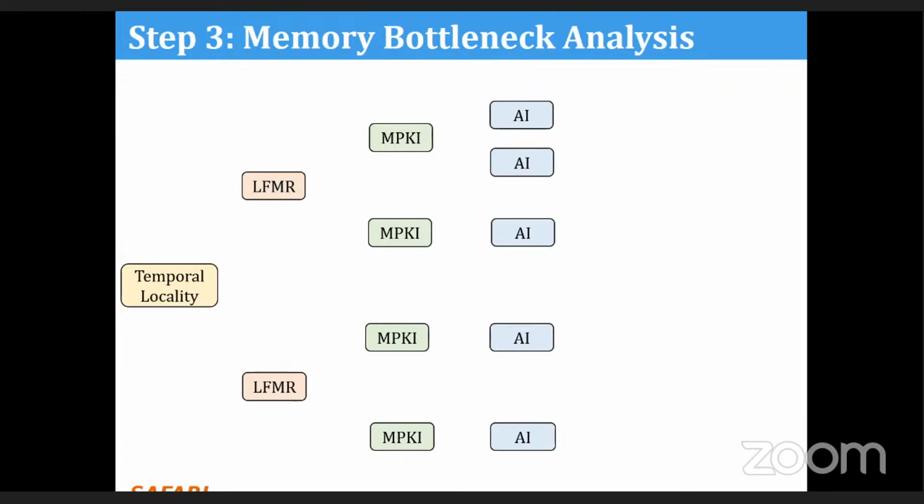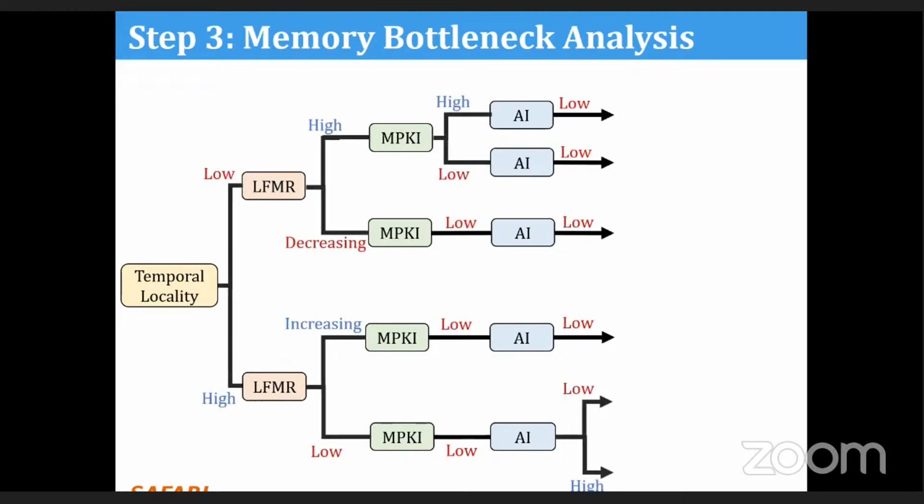The reason is that the 2 configurations we are evaluating, the host and the PIM configuration, both have an L1 with the same characteristics. And normally L1 is where most of the spatial locality is captured. So that's why in our analysis, spatial locality is not so relevant, and temporal locality is more.